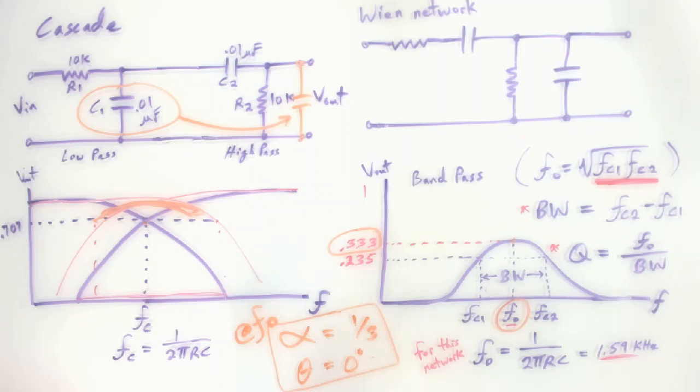oscillator that we'll look at down the road, which is actually what put Hewlett-Packard on the map. They found a way to use a Wien Bridge network to create a Wien Bridge oscillator, and then he did one cool little trick with a simple lamp, like we used in the first week of school. And they used a simple incandescent lamp and the fact that its resistance goes up as current goes up, and they used that in a feedback network with the Wien Bridge feedback oscillator.